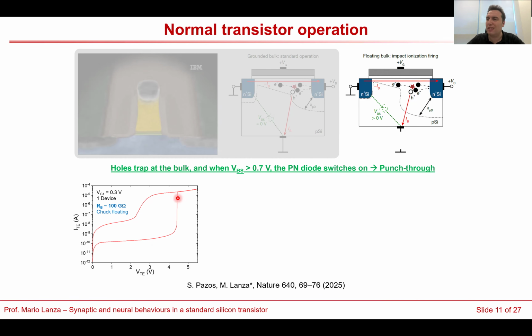It produces this kind of highly nonlinear transition, which is what we need. However, when we ramp the voltage down, this transistor is still on. It tends to recover, but it takes a lot of time to reach the initial state because these holes here have no way to leak, and it takes a lot of time.